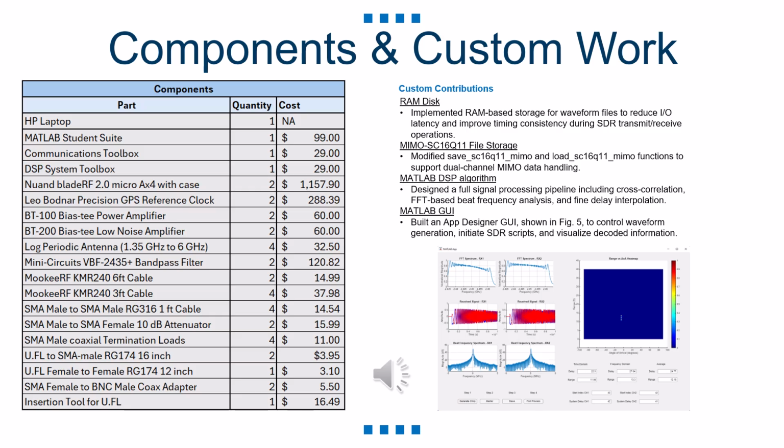support dual-channel MIMO functionality. The MATLAB digital signal processing algorithm was developed and provided coarse and upsampled delay estimation using cross-correlation, as well as beat frequency analysis and angle of arrival estimation using the MUSIC algorithm. Finally, a graphical user interface is created to help streamline the cumbersome process.